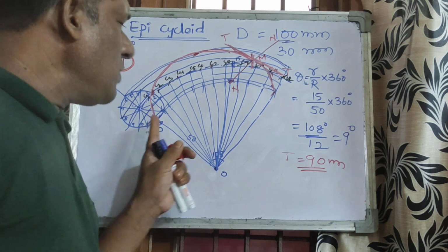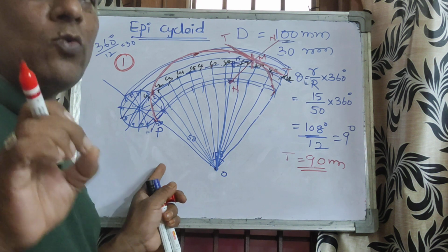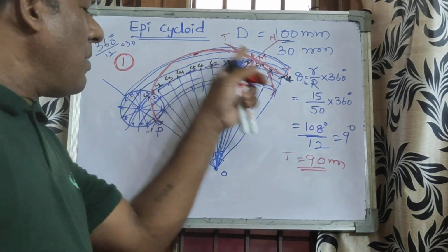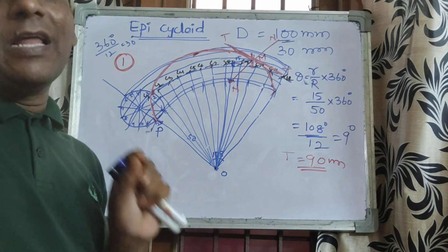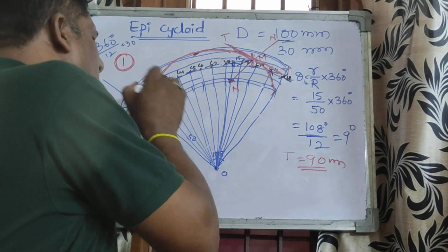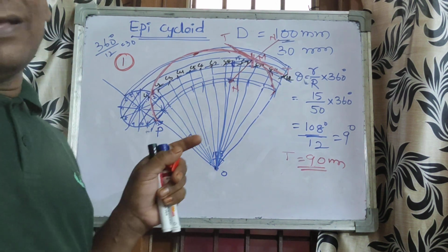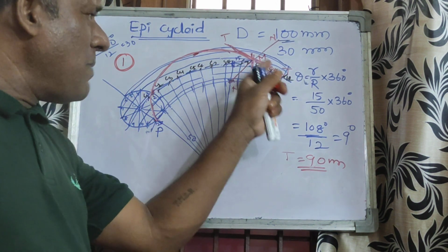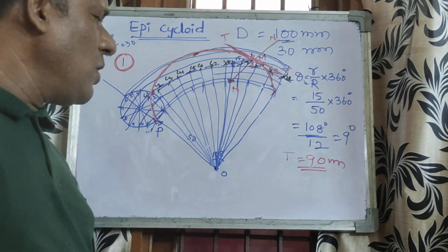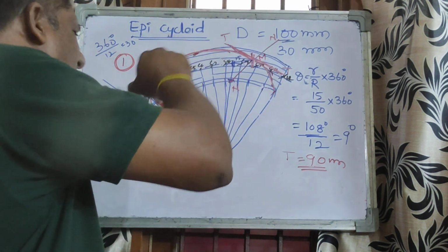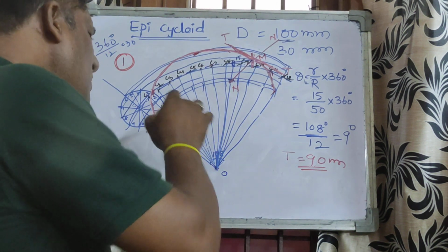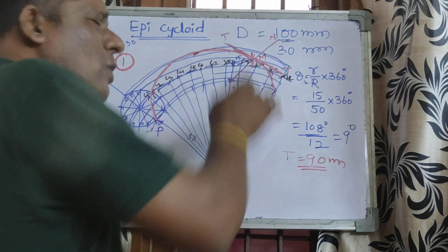And the second point is you must maintain the difference between HB and 2H pencil. And the third point is give all the numbering and dimensioning with HB pencil clearly. Some students give it so lightly that it is not possible to see or read. But the numbering, dimensioning, centers, everything is important. That's why you give it with HB pencil. Whatever extended lines are there, these are all with 2H pencil. And after completion of this, go for the actual solution.